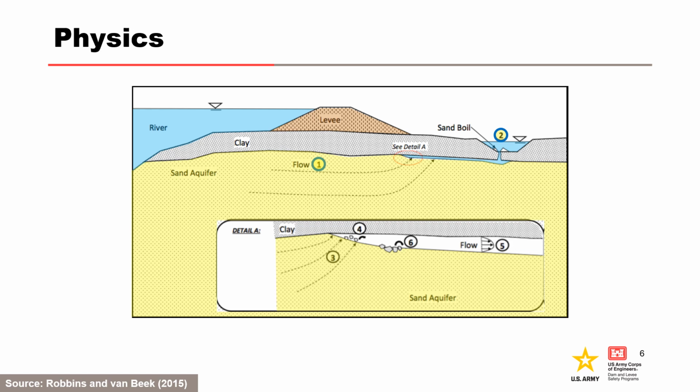This figure is an illustration of the physics of backward erosion piping. The process includes 1. Darcian flow, 2. Exit-related hydraulic conditions such as orifice flow, pipe flow, or constant head boundary conditions, 3. Liquefaction or fluidization at the pipe head due to concentrated flow, leading to 4. Occasional bursts of high suspension solids into the pipe, 5. Laminar flow conditions in the open pipe which cause 6. Sediment transport along the bottom of the pipe. All 6 must be occurring simultaneously for piping to progress to failure.